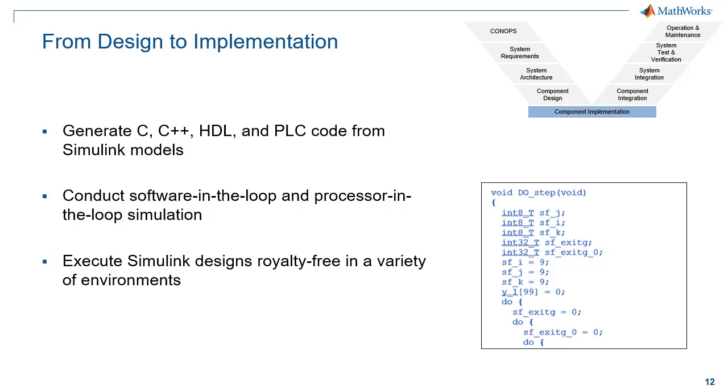Yes, you are building software when you build a Simulink model, but that simulation can only be executed on a machine that is capable of running MATLAB, which means it needs to be the right operating system, have the right hardware resources, and have the right licensing capabilities. If you want to run what you've built in another environment, then you're going to need to get it out into some other language. And what I want you to understand is that we have ways of automating that process.